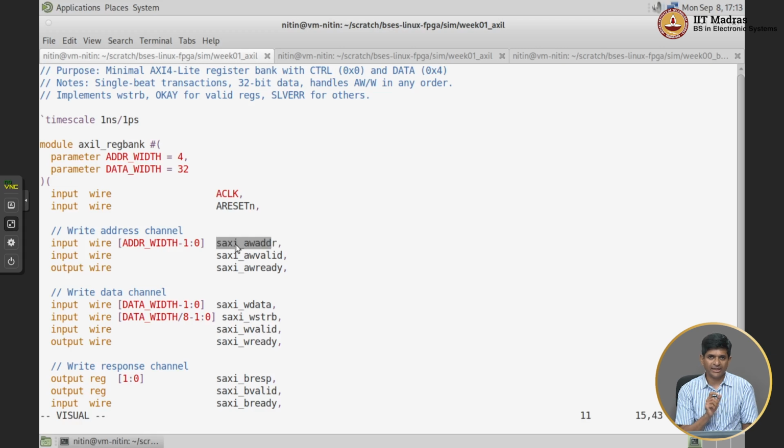So what that from prefix is telling Python is look for signals that have the name SAXI underscore, and all of them basically correspond to a bus. Look for the appropriate write address, read address, AW address, valid, ready, all of those, and combine them together into an object inside Python which corresponds to an AXI bus, okay. So it sort of does a lot of interesting magic out there behind the scenes.